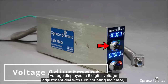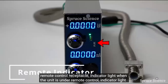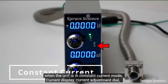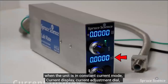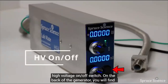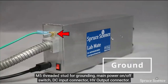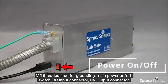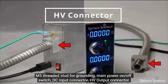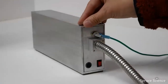Voltage adjustment dial with turn counting indicator. Remote control receptacle. Indicator light when the unit is under remote control. Indicator light when output is in constant current mode. Current display. Current adjustment dial. High voltage on-off switch. On the back of the generator you will find M5 threaded stud for grounding. Main power on-off switch. DC input connector. High voltage output connector.